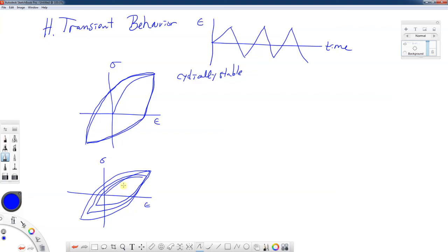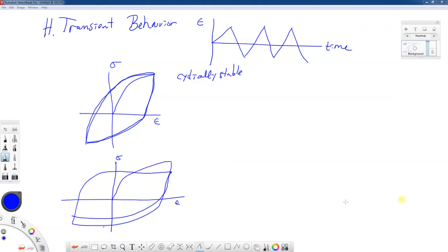Well, let me do it smaller and smaller stress levels. I'm in strain control. Let me redo that plot. Okay, so in strain control, I'm getting to the same levels of strain, but I may end up dropping my stress level with continued cycling. This would be known as cyclic softening.